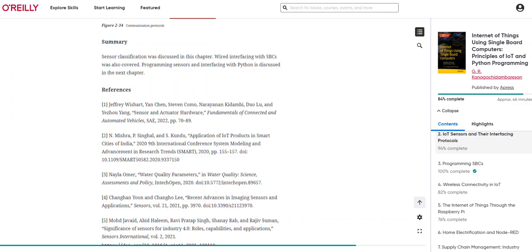Let's briefly explore an example. Let's say we want to interface a temperature sensor using I2C. We connect the sensor's SDA and SCL lines. Remember we said that on I2C there's 2 lines, to the corresponding pins on the microcontroller. In our microcontroller code, we initialize the I2C bus.